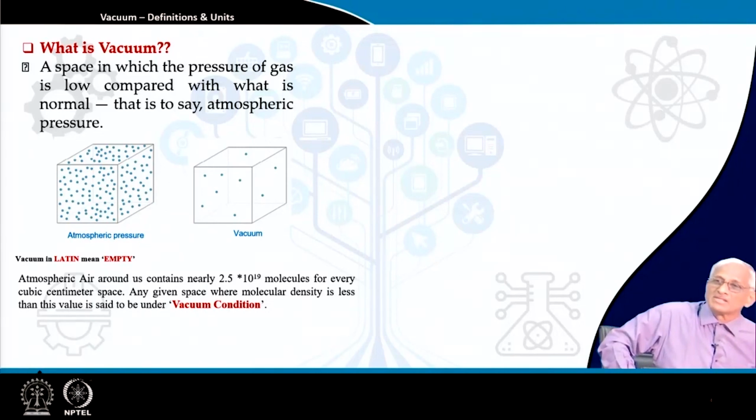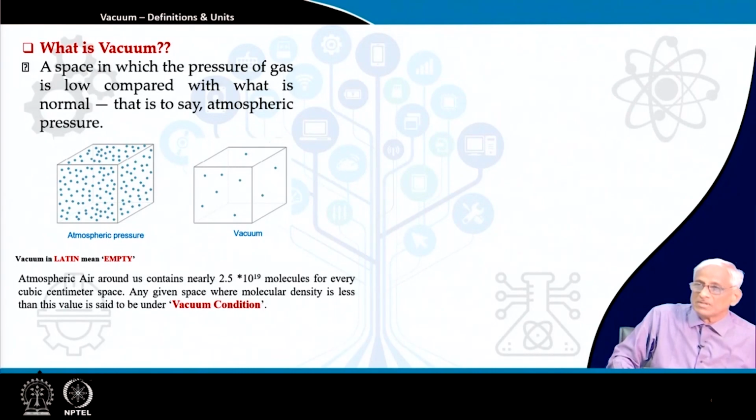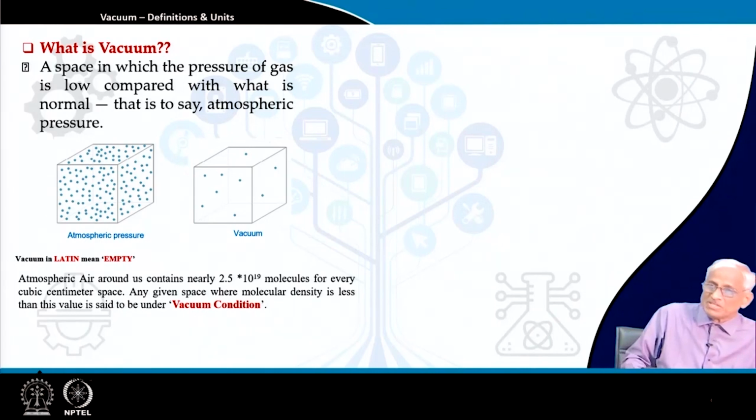For example, ideal gas. When is a gas ideal? Only under very low pressures. So, vacuum conditions are ideal for studying ideal gas behavior, PV is equal to nRT. At higher pressures, it is not allowed. Most of the engineering thermodynamics deals with high pressures, but their ideal gas equations are suitably modified using various correction factors, but here PV is equal to nRT is highly valid.